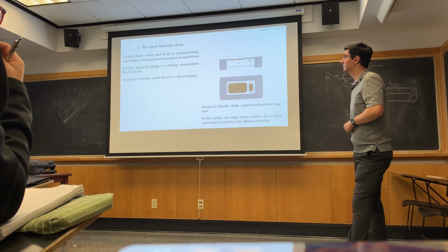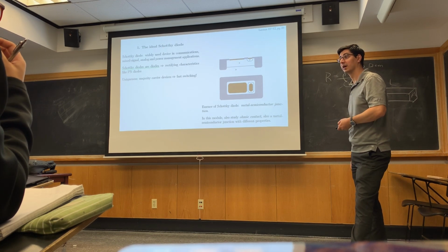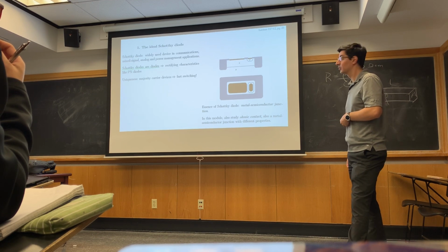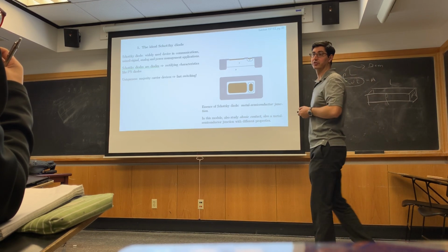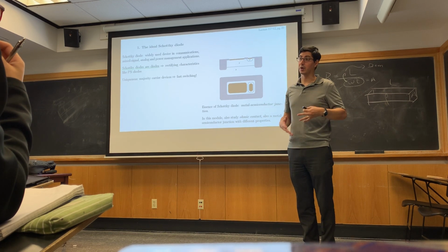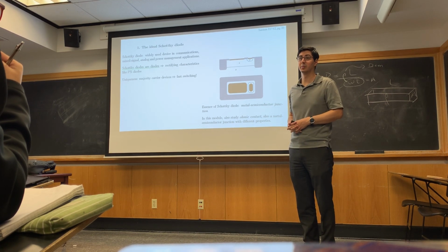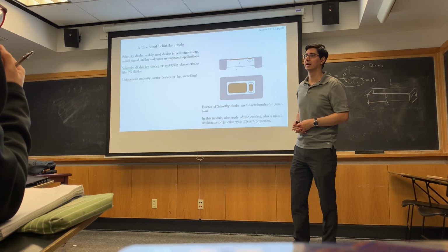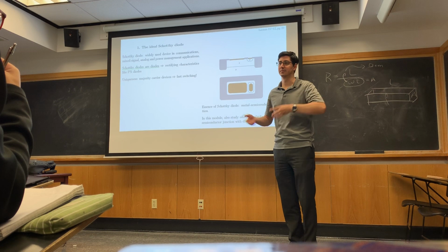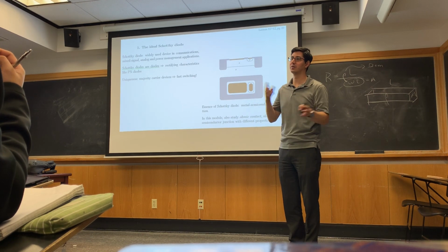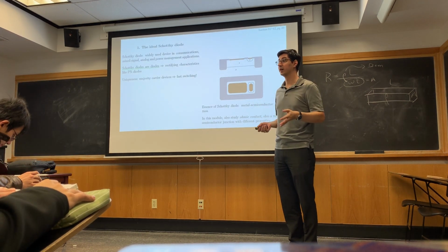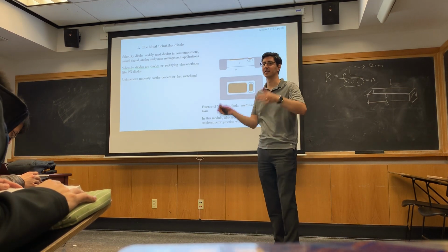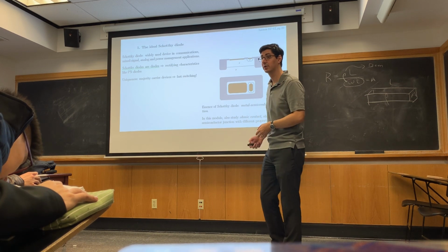So at the end of this topic, we're going to discuss ohmic contacts, okay? So when we take a metal semiconductor junction, instead of having it rectify, we're going to want it to conduct as much as possible, so that whether we apply forward bias or reverse bias across it, so much current flows that even if it kind of rectifies in one direction or another, it's so much more conductive than the rest of the circuit or the rest of the device that that part dominates, and the contact is just the contact. Okay?